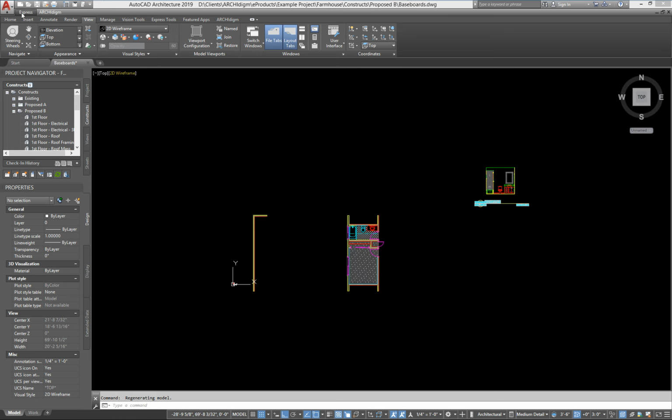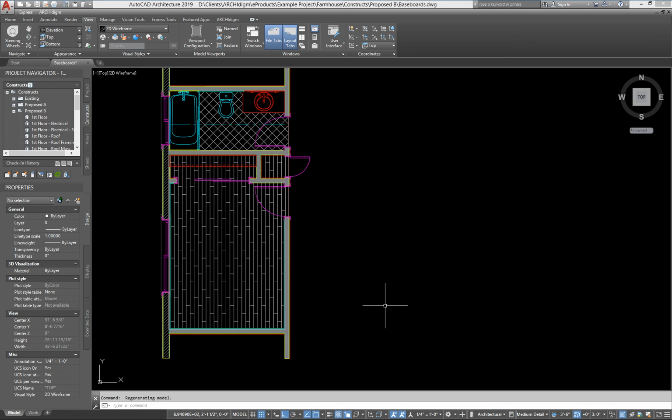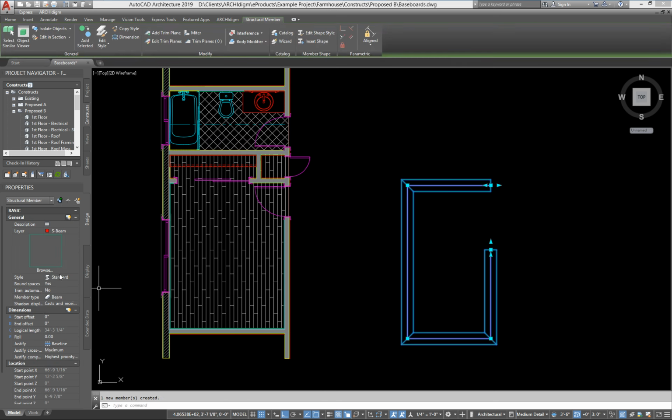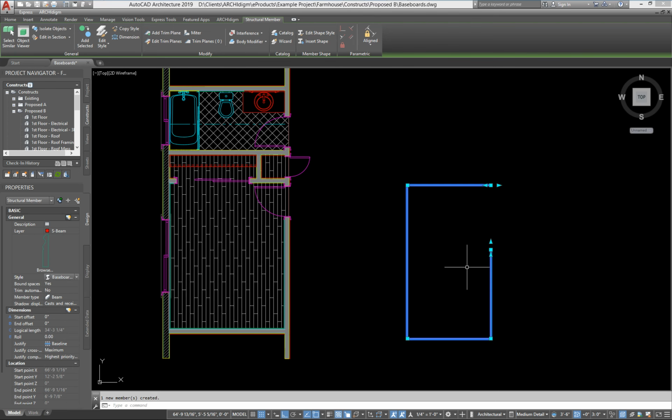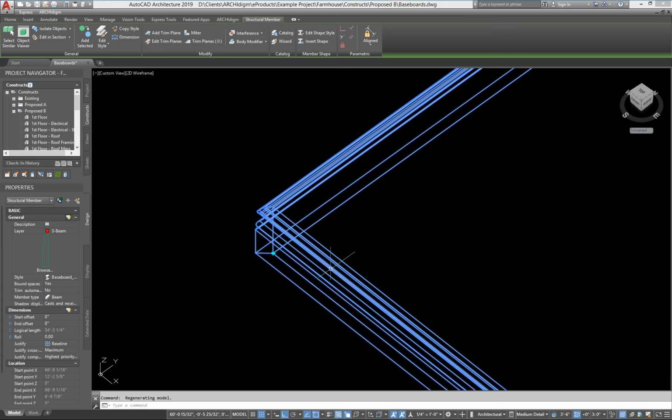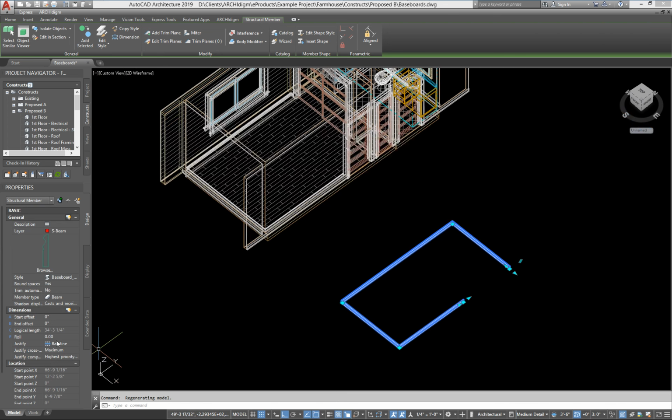And again, let's see. Finally, if you have a room that goes something like this and like this, let's say, and it comes back like that, you can actually do a beam convert, and you can select a non-closed polyline and convert it over to your baseboard. So that's one way that you can make a rapid baseboard. Oh, it's inverted.